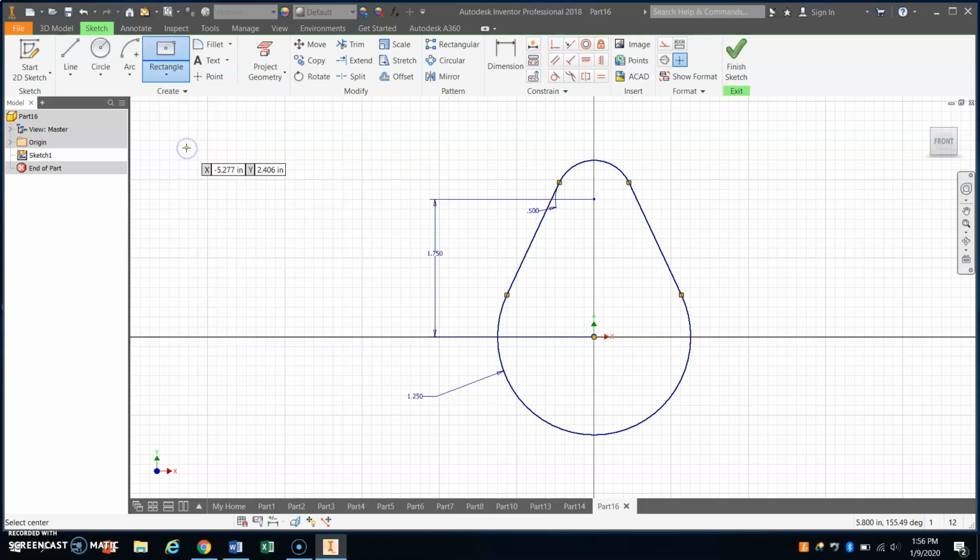With this particular tool, we're going to identify the center of the rectangle and then make our rectangle go out from there. So the rectangle itself is not touching that center point. That's going to be the center. And you can see the little construction lines, those dash lines that show me the connection of the two diagonals, and that's the center point right there.